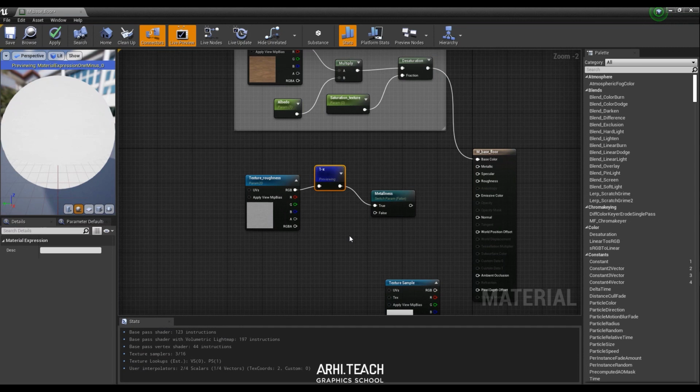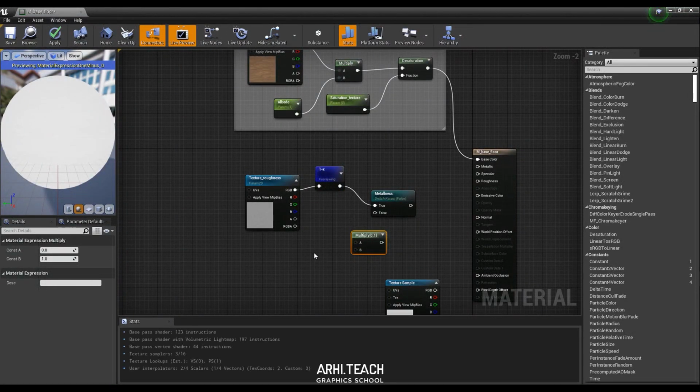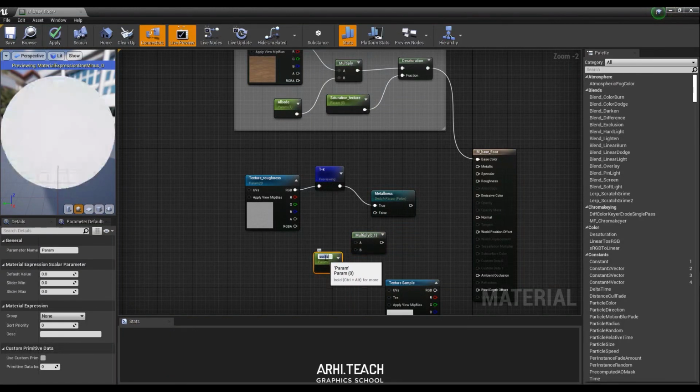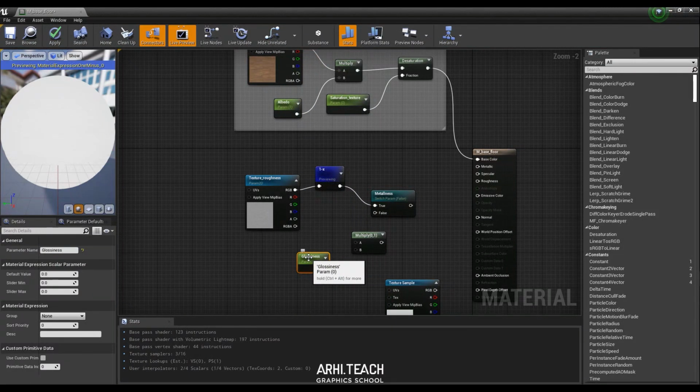As always, we hold down M, left click, and multiply appears here. Next we have a controlled parameter. We hold down S, then left click, and here we'll have glossiness. But this is, if I may say so, such a blend between glossiness and metalness. Ignore these parameters. Electrics, dielectrics, metalness or glossiness, these are types of shaders. The most important thing here is that we need to focus on parameters that will change so that we can easily get the material we need in 2 clicks.